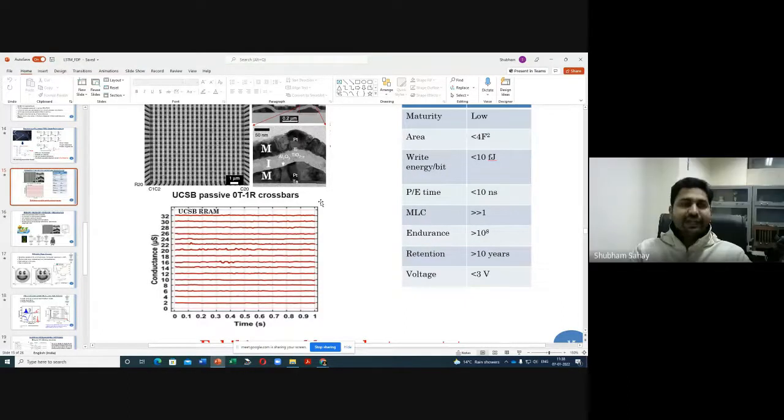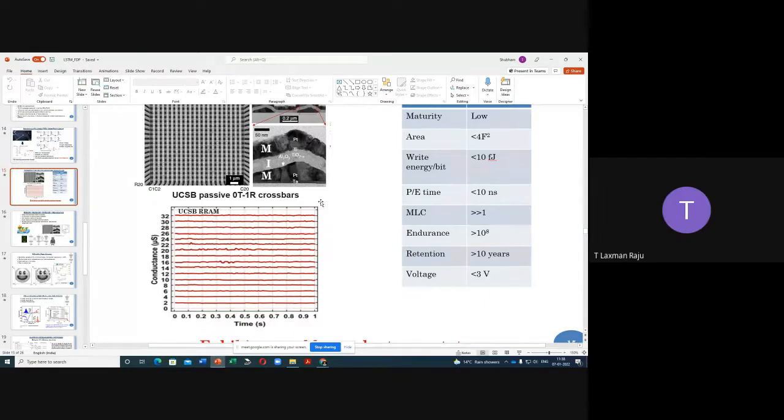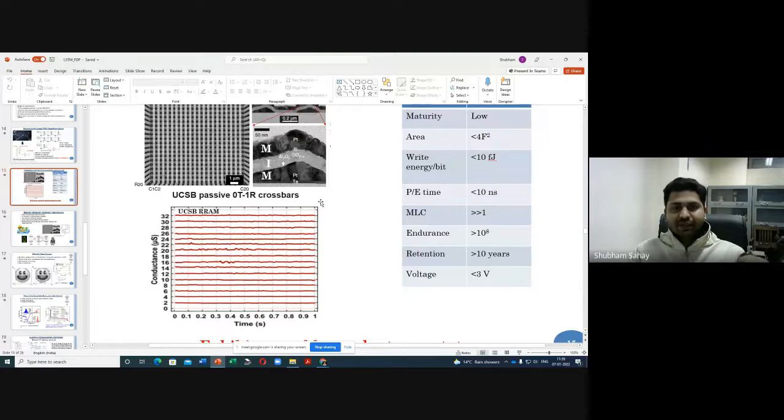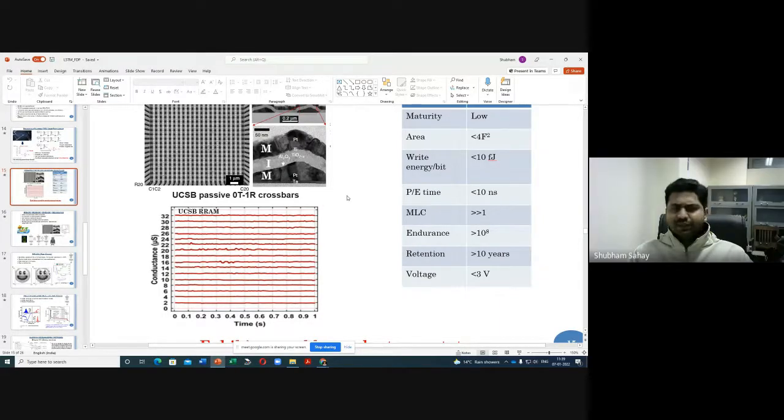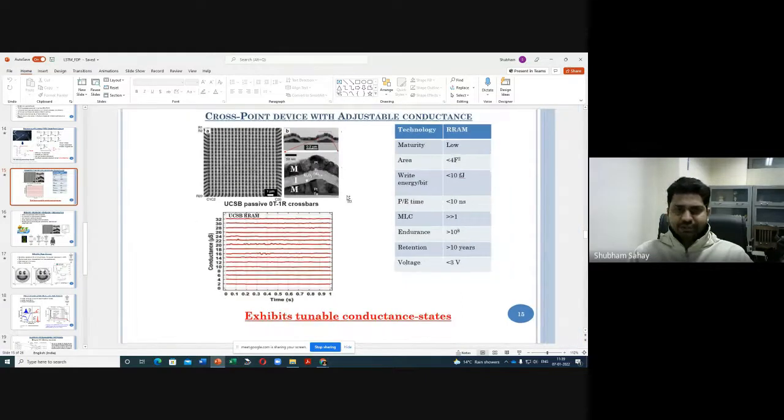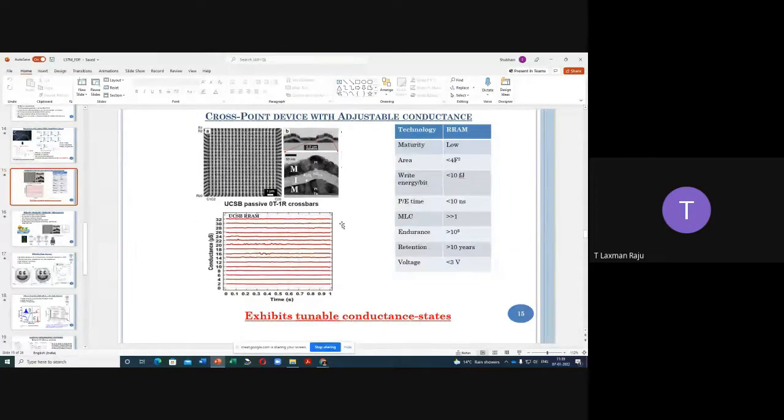Yes, those we definitely take into account. We take them as perturbations. Here we were using a standard normal function. We characterized around 3 million devices for more than a million cycles, and based on that we formed the Gaussian function and fit that function to our experimental data. That is how we did it. Does this all work at 300 Kelvin, or is there any temperature variation? This was all at 300 K. This wasn't any high temperature measurement. Okay, thank you for the brief explanation.